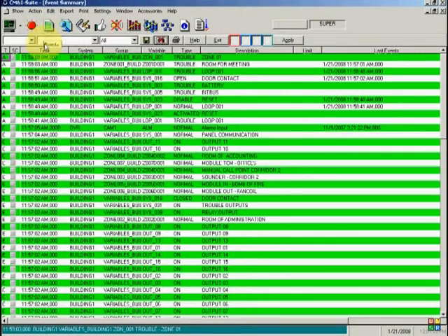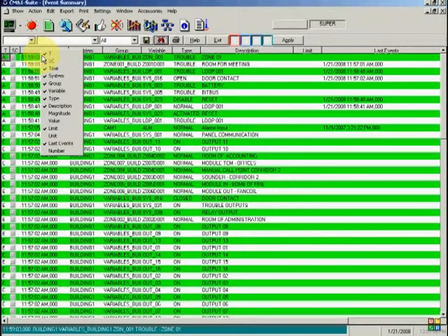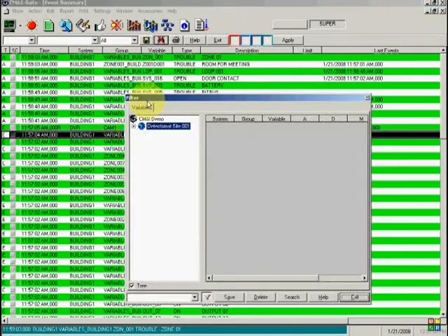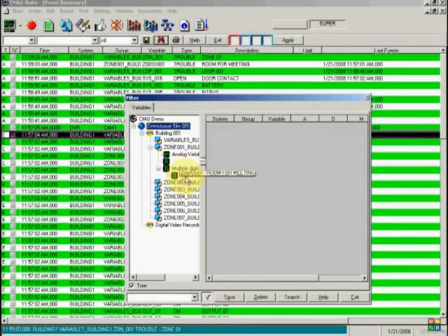The Daily Events screen shows the events of the day. Events are all alarms, operation actions, and significant changes on variable states. On the left side of the screen, a letter identifies the origin of the event. Like the alarm screen, the columns are optional and there are buttons and combo boxes to implement filters and operator actions.